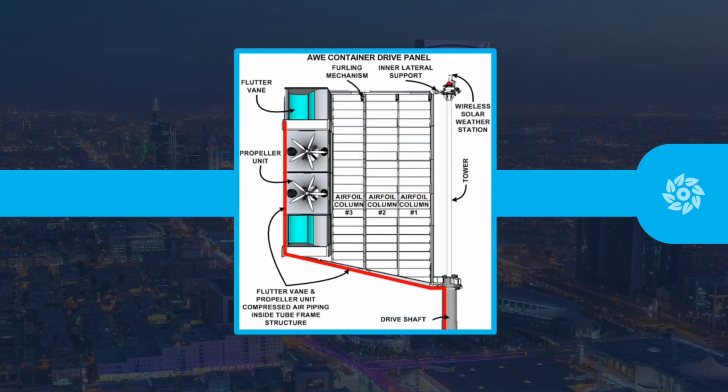These wind and tangential air flow harvesting devices can operate without the drive panel structure rotating. The flutter vanes, 3 curved panels, will rotate in a 2 miles per hour, 3.2 kilometers per hour wind. Flutter vane air compressors are housed below and are operated in series using clutch systems to engage each compressor based on the airflow speed. In a 2 miles per hour wind with no structure rotation, only one compressor is operated and the compressed air is piped to storage tanks housed within the propeller units.